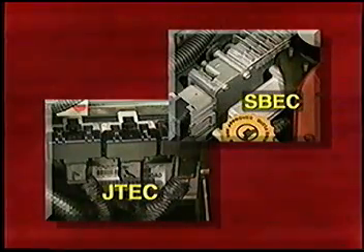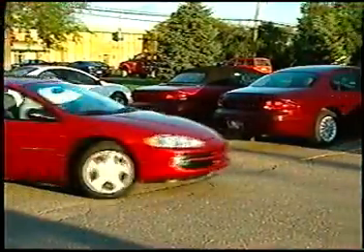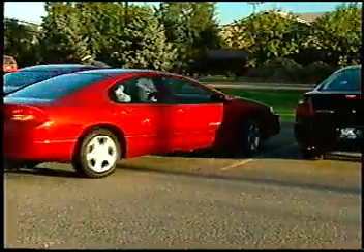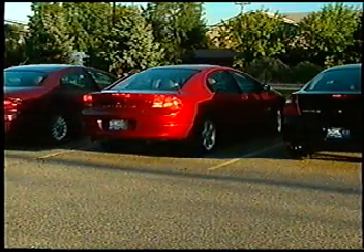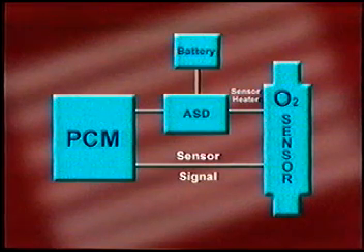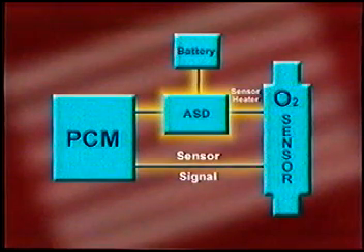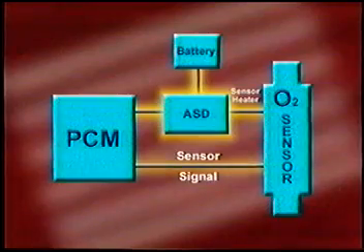The conditions for the O2 sensor heater monitor to run will depend on the PCM that the vehicle uses. On vehicles equipped with the S-BEC, the test is run after the vehicle has been driven and then shut off. After the O2 sensors have cooled down, the PCM turns the heaters back on and looks for a change in diagnostic voltage, which indicates that the heaters are functioning properly.